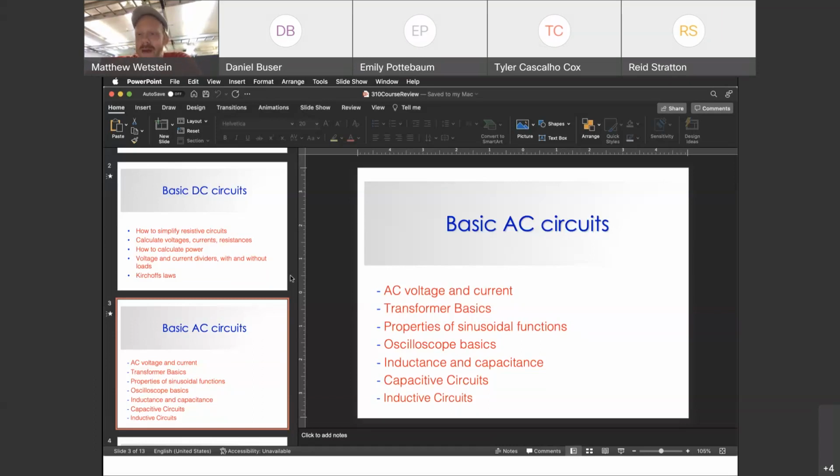Understanding what inductance and capacitance are. And when I say that, we're interested not only in inductive and capacitive reactance, but also inductance itself. I might ask you, what's the equivalent inductance or capacitance? And note that the equivalent capacitance is different than the equivalent capacitive reactance, and it even adds differently, because capacitive reactance adds in series and adds as the reciprocals in parallel, whereas capacitance adds linearly in parallel, but as 1 over the sum of the reciprocals in series. So understanding those distinctions is important.